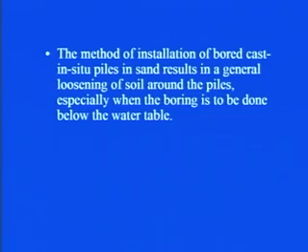This aspect we have already seen, although it is bored cast in situ piles, in which you create a borehole or a void and then you install the pile in that. However, in case of sand, when you create the borehole or that void, the soil around the walls of the borehole gets loosened. Because of that the problem occurs.